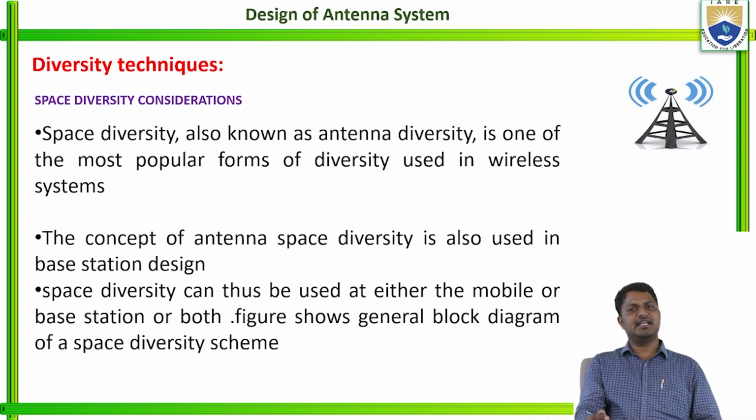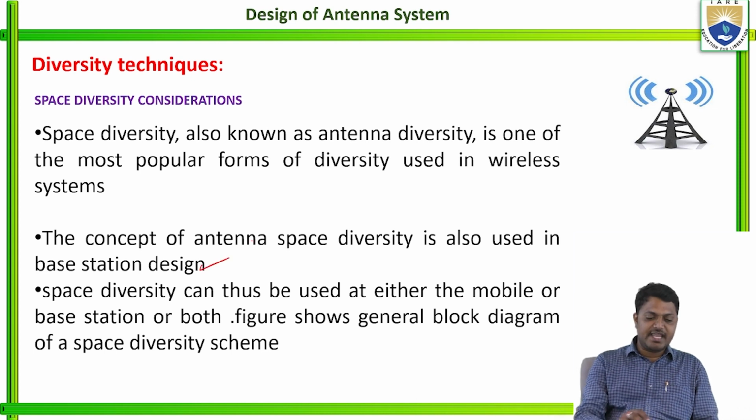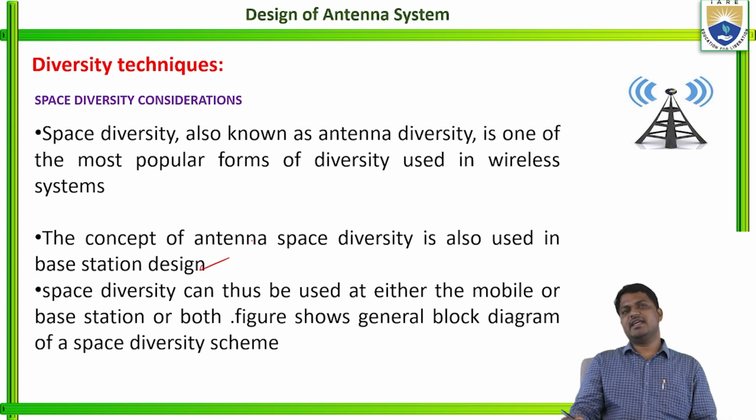When we are designing an antenna system, we have to consider the diversity techniques also, right? So this space diversity consideration is also known as antenna diversity, the most popular diversity used in wireless systems. The concept of antenna space diversity is also used in base station design. So space diversity can be used in either the mobile unit or base station, or in both.